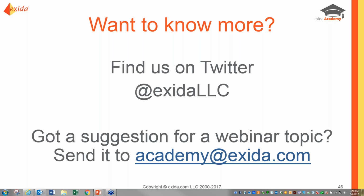How does 13849 differ from 61511? Those are for two different industry sectors. I think there's a lot of commonalities in what's required. Mostly they're tailored for specifics of that industry. 61511 is, of course, for the process industry like we see in chemical plants, where the requirements in nuclear are very different than they are in a chemical plant. And then, of course, in the automotive or machine sector, you've got continuously running machines, so there's different unit ops. So the standards are tailored a little bit for those kinds of unit operations that are characteristic to those industry sectors.